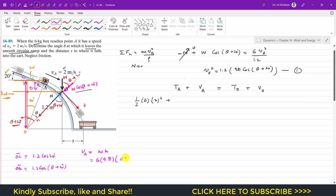So this is the gravitational potential energy at point A. This is 6 into 9.81, and OC is 1.2 cos of 20 degrees minus 1.2 cos of theta plus 20 degrees. And now we can take 1.2 common as well, so that will be 1.2 (cos of 20 minus cos of this).